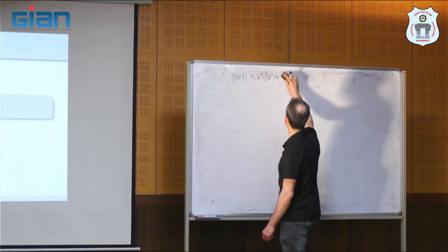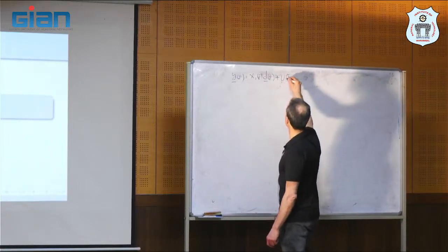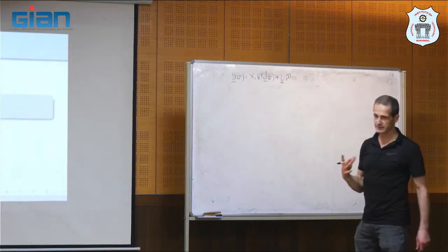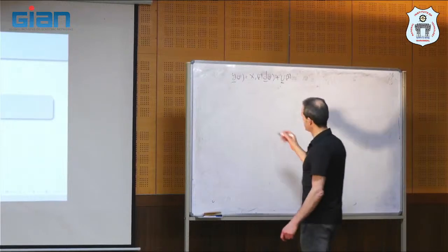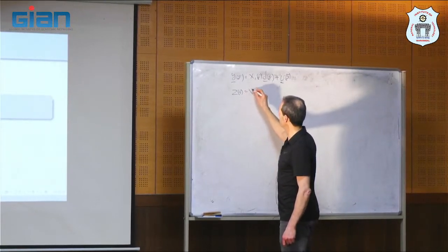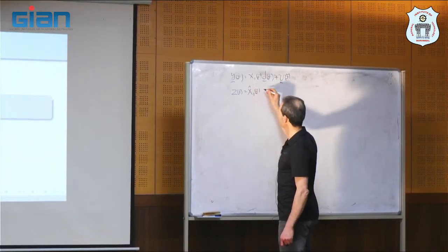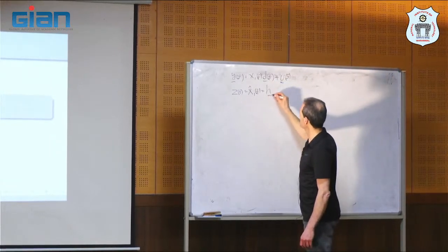This is the vector of noise for the frequency f in all the M sensors, okay? And then we try to find an estimate of the desired signal in the reference channel, the reference sensor, by obtaining a linear filter that looks like this.